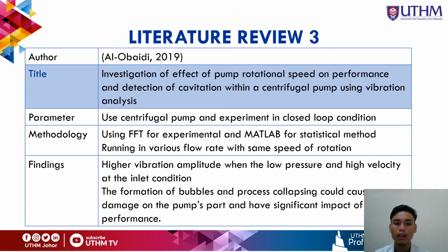It was run at various flow rates with the same speed of rotation by changing the size of the pump. It showed higher vibration amplitude when there is high velocity at the inlet and low pressure condition. This condition generates the formation of bubbles and can impact the performance of the pump. The vibration may occur from the formation of bubbles in the pumps when running.